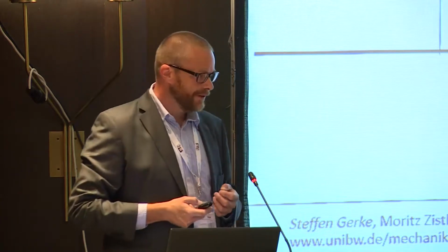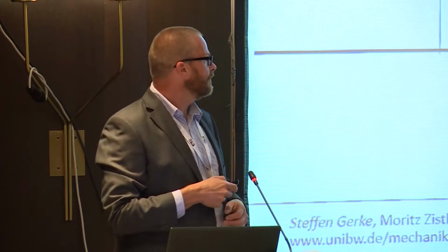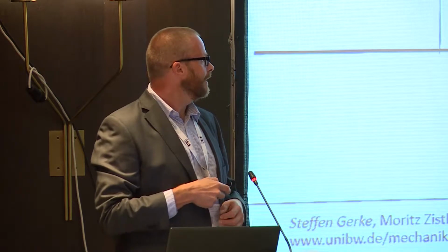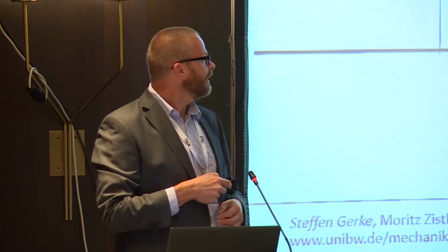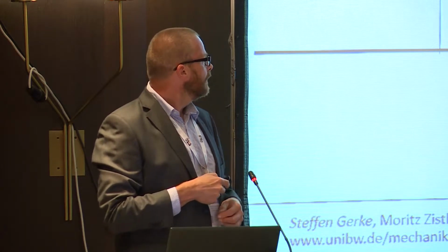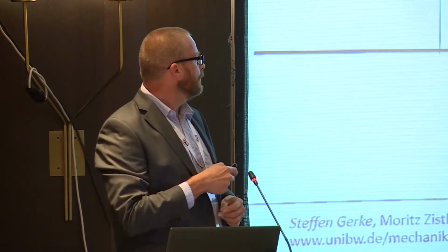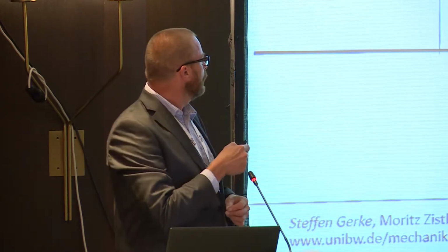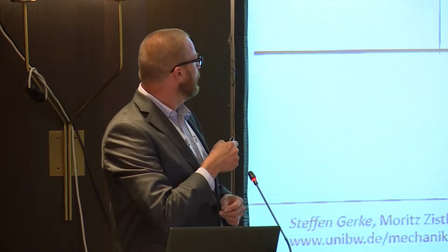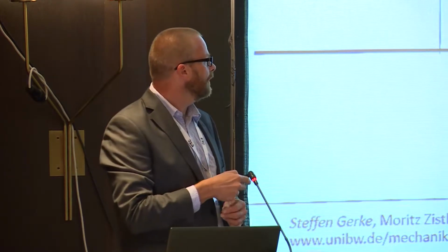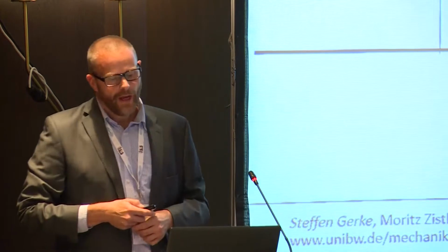What is damage in our understanding? Damage is an ongoing process which leads to final fractures in ductile matter. So for high positive stress biaxialities, we have void growth as the leading damage mechanism, and we have the appearance of micro shear cracks below a certain cutoff value. Below that we have no damage occurrence, and we have this intermediate zone.